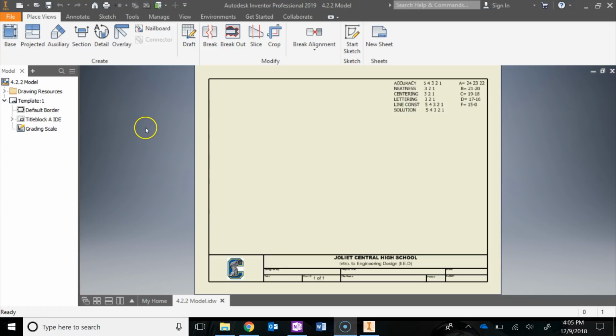After you're done saving, the next thing you should do is fill in the title block with the proper information. So if you look down here, mine is all filled out. The only thing I didn't add in was the scale yet, because I'm not quite sure what scale we're going to go with to help make sure this thing fits in there. So I will come back and do that at the end. Remember, your title block information is in the field text area if you forgot to do that. Remember, that's all standard stuff that you need to do at the beginning of every drawing.